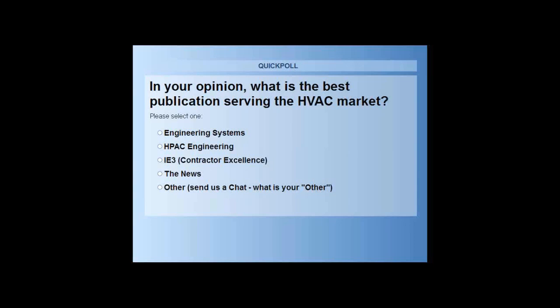Lisa, let's take another question from the audience as well. The next question is, what do I tell an inspector or AHJ who questions the installation in a packaged rooftop unit? Okay. Well, first, the principal operation of duct smoke detectors is that pressure differential between the sampling tube and exhaust tube. If you have the recommended pressure differential, then you know that your detector installation should perform correctly.